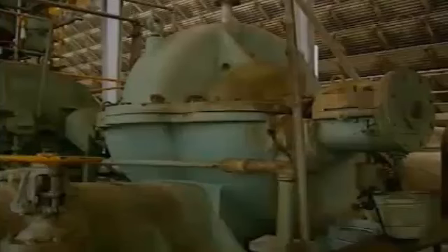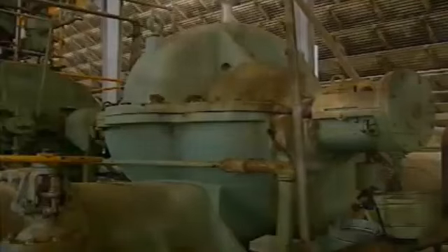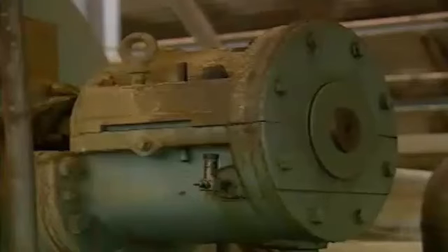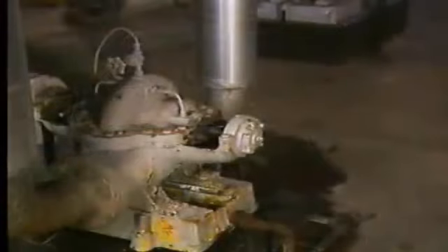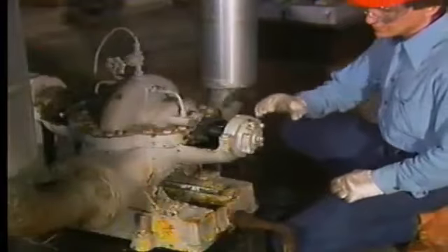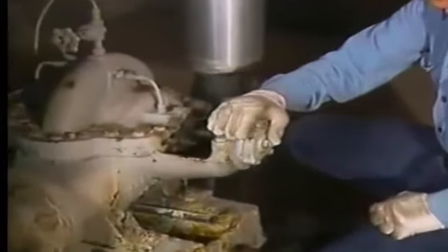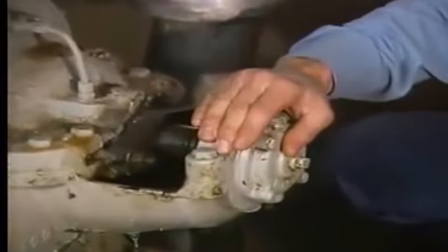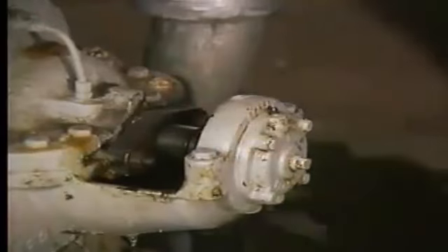A bearing doesn't reach its normal operating temperature until after the equipment has been operating for a while. The amount of time that's required varies with each piece of equipment. After a bearing reaches its normal operating temperature, the temperature should stay relatively constant unless there is a change in operating conditions or the bearing malfunctions. Changes in bearing temperature can occur for a number of reasons. However, a sudden increase in the operating temperature of a bearing that cannot be explained could indicate a serious problem, including the possibility that the bearing has failed.